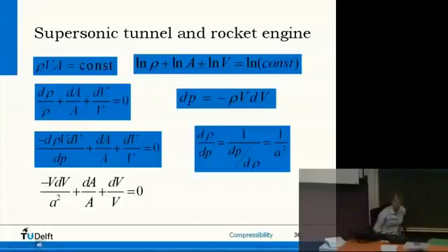Now it's a bit intriguing, right? Why is the Mach number 1 in the throat? And why is this the other way around? For supersonic flow, if your area goes up, your speed goes up as well. Well, there's an indicative analysis in Anderson I want to share with you to show you how you can get an idea about that. There we start from mass conservation. For compressible flow, so rho V A is constant.